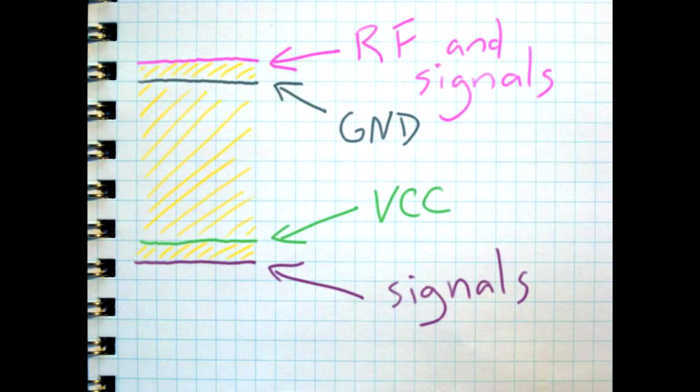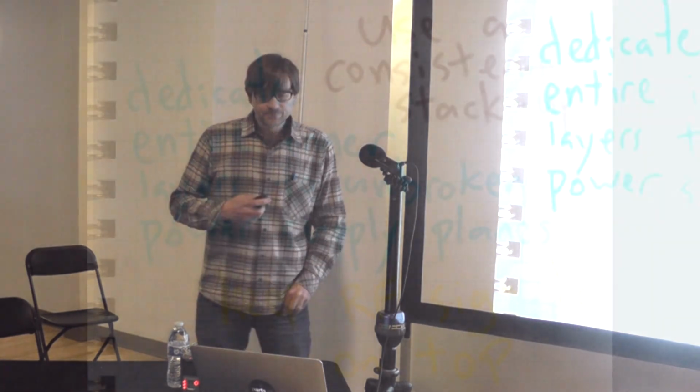It only took a couple weeks, and I had some 4-layer PCBs, an RF design that actually is featured in this presentation because I had it in time to do that, even though it was just done a couple weeks ago. So, do 4 layers. It makes your life a whole lot easier working with RF. And it's pretty accessible to be able to get 4 layers or even more layers these days in a PCB.